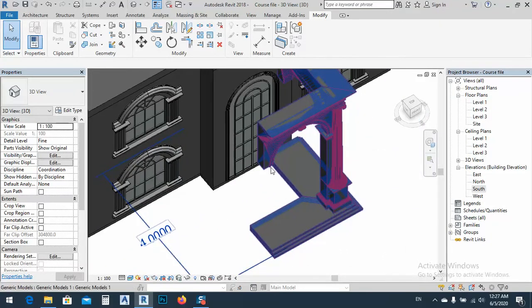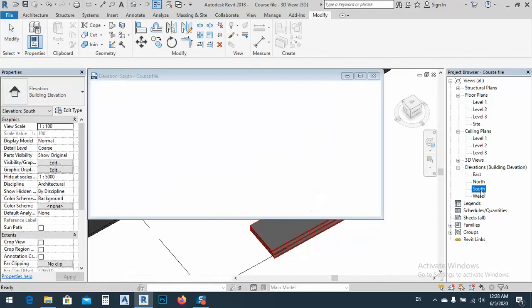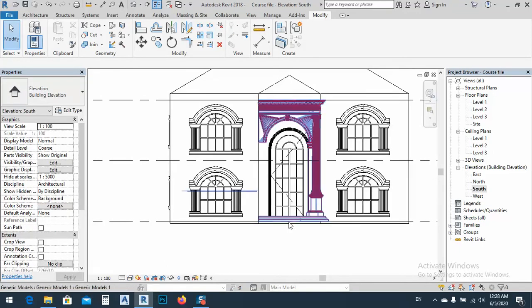By the way, I can arrange this one, or I can make it L shape in AutoCAD, or I can just copy it or mirror it here. But I don't suggest you make a mirror, because if you use mirror for that, you will lose, or your quantity of material will not be correct later. Anyhow, it's only for tutorials. That's why I'm using this one.